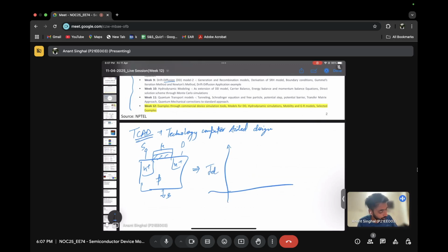So if it is looking like this, what is the x-axis? If it looks like this, is it VG or VD? Okay, so this is IDVG, because what we have is a threshold voltage. Before this, the device is turned off, and after that, the device turns on. The IDVD looks something like this, if you remember.